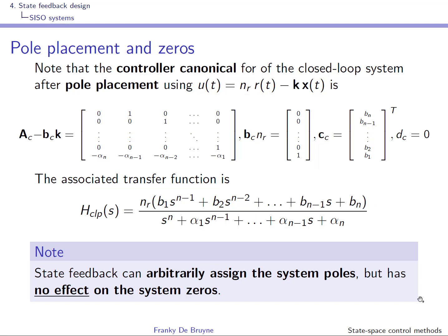Well, you can see, for instance, that in pendulum or inverse pendulum type systems, there is a zero in the transfer function to the right of the imaginary axis, and this zero that is placed to the right of the imaginary axis causes a so-called inverse response.